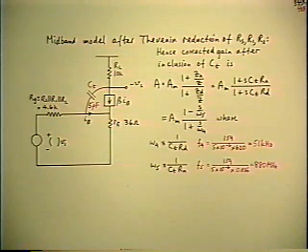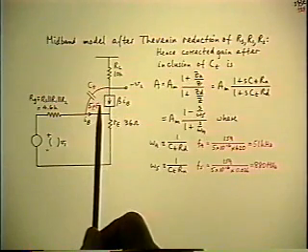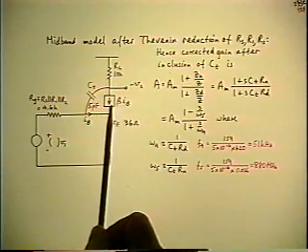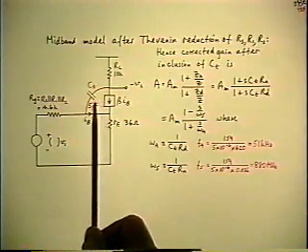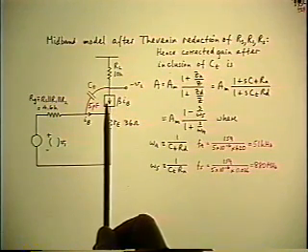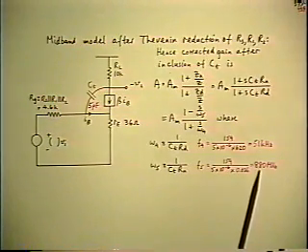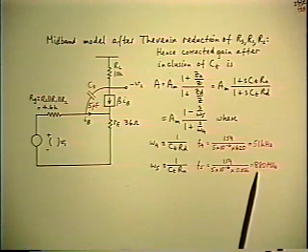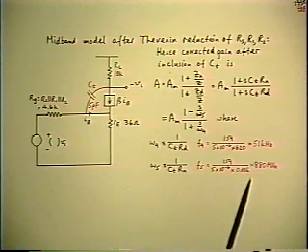But it's not too hard to visualize some circumstances where the numbers may be radically different. For example, suppose the CT were not 5 picofarads, but 5 nanofarads. Not because the transistor would be that lousy, but you often purposely put a capacitor in that position, externally. Okay, so if the capacitor is 1,000 times bigger, this is now 880 kilohertz. Now it's down to a range where it may get in the way of some things you're looking at.